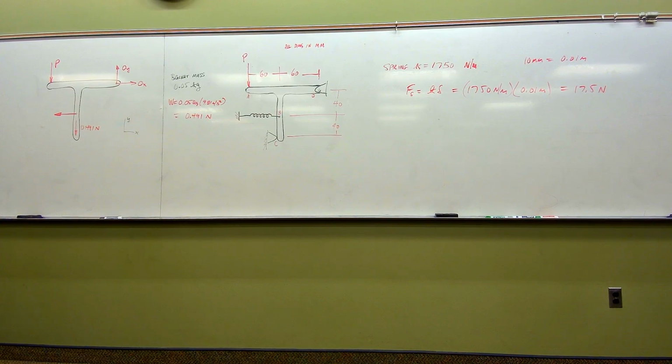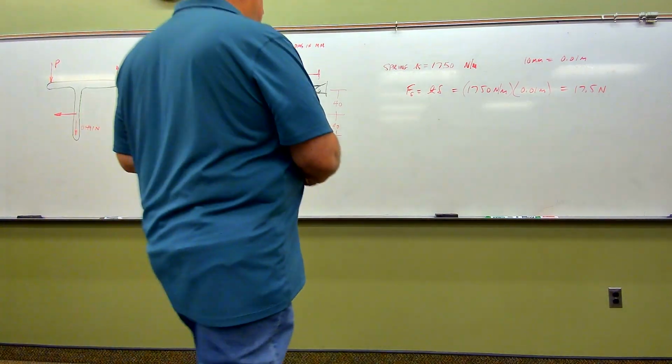See, tension springs actually need an initial amount of force to get them to start deforming. It takes an amount of force to start the deformation, then after that, it's K delta. So the true equation for an extension spring is K delta plus Fi, or force initial. The authors ignored that in this case here. They just figured you don't need to know that for now, I guess. But if somebody has already worked with springs, you might be looking at that thinking, wait a minute, I'm missing something here. Yeah, you would be right in that case, but they don't go down that path.